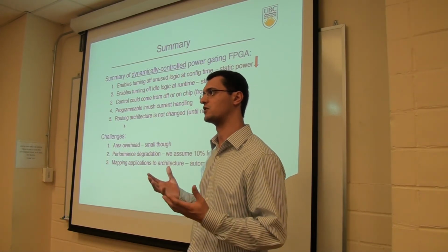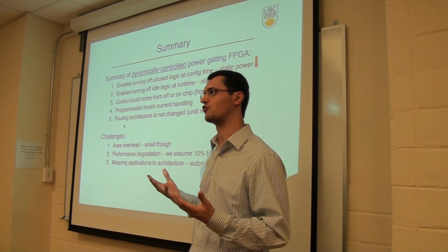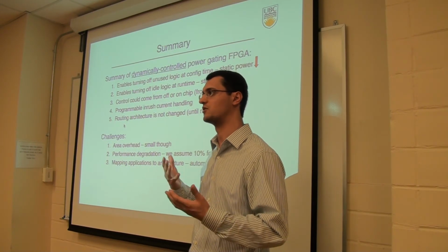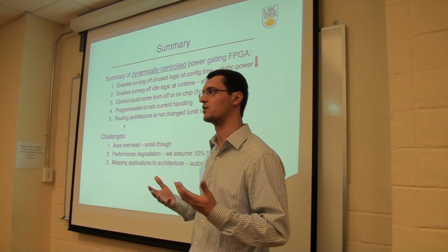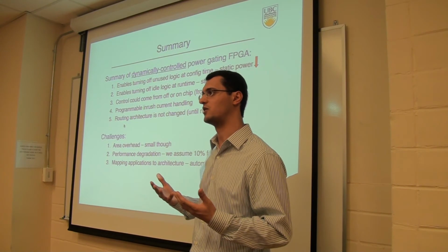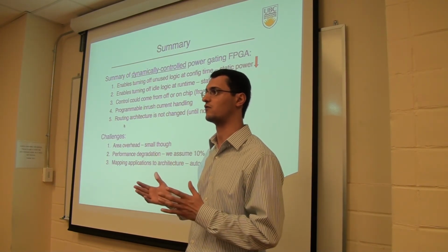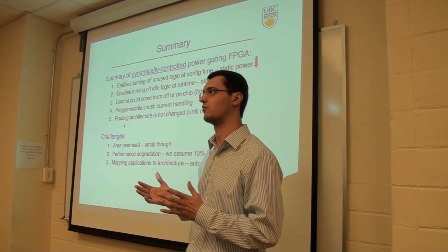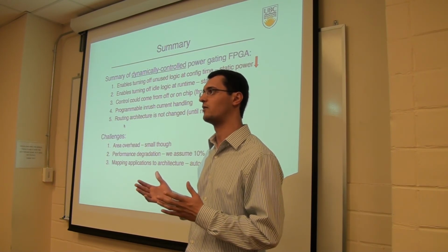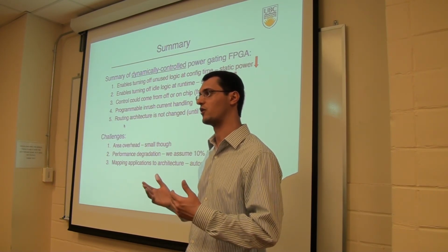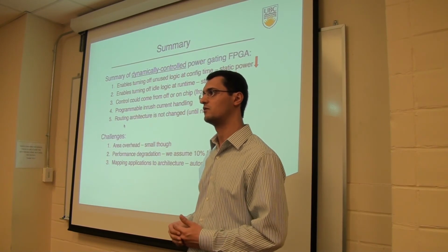It will be less than double, because some of the resources are shared, like they share the same capacitors, because of the statistical behavior of the things inside the region. So if you double the region size, this doesn't mean that you will double the size of the sleep transistor. It will be less than double. This is why the area overhead decreases as we increase the region size. Does that make sense?